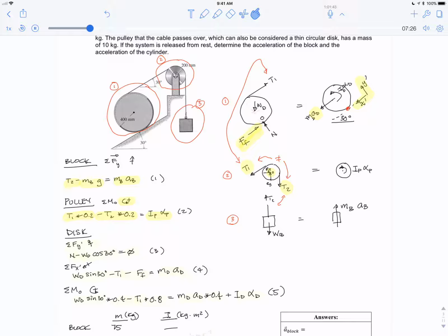So if you look up here near the picture of the free body diagram, I've drawn in what I've considered positive X and positive Y. Because normally we think of X as horizontal and Y as vertical, I said X prime and Y prime to show that these are the rotated 30 degree axes. Okay, so I'm now going to take the components in the Y prime direction. I'm taking, as shown in that picture, up and to the left as positive.